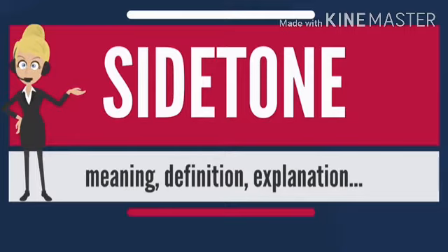Side tone is also used on voice radio equipment to give the radio operator confidence that they are transmitting over the radio. The side tone audio is typically derived from the transmit audio circuitry. In aviation, the loudness of the side tone heard in a pilot's helmet or headset may be adjusted to suit personal comfort, although this may lead to communications problems since the pilot will be largely unaware of how his transmission sounds to the recipient. The ideal level for the right psychoacoustic behavior is reported to be about 7 dB below the received audio, according to RTCA specification DO-214.